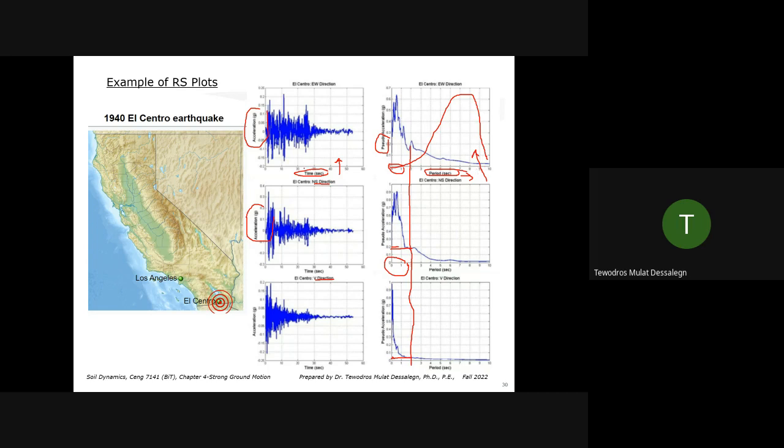Now, the time history is usually very costly. It takes a lot of time because it's working at a very small delta. In the response spectrum, it's very fast because what the software does is it quickly determines the period of that structure and picks up the corresponding acceleration. That's it. It applies it at all the masses or the finite elements corresponding to that.